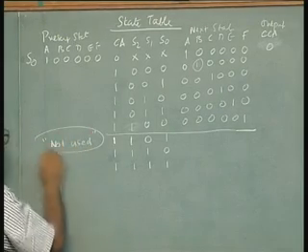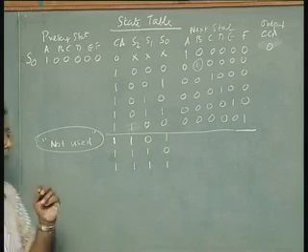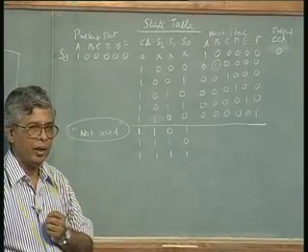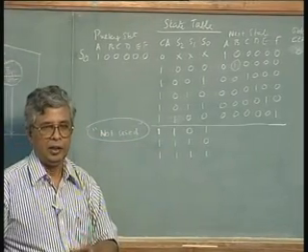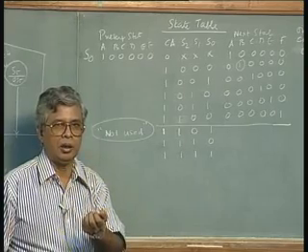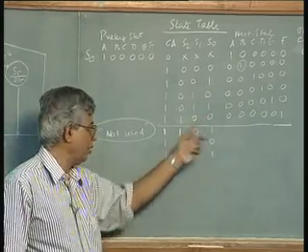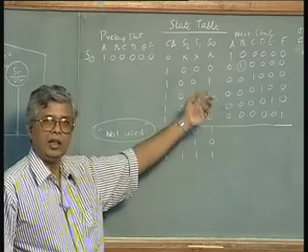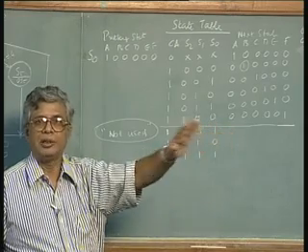There are 2 ways of doing it. You can make them as don't cares. If you make them as don't cares, what happens is the design will become flawed because some random number will come, and also possible there is a glitch occurring. If you design the state machine, sometimes one of these not used inputs can lead to a state which is a permitted state, and then it may dispense a merchandise which has not been selected.